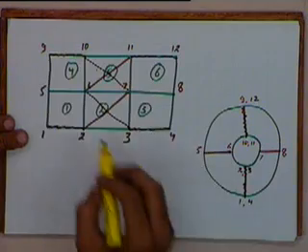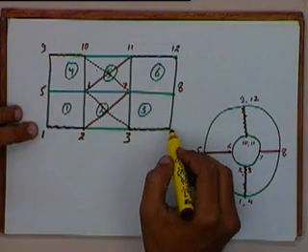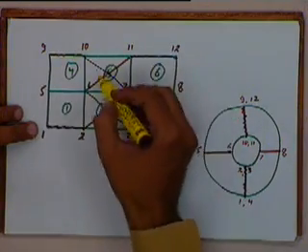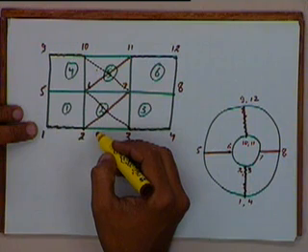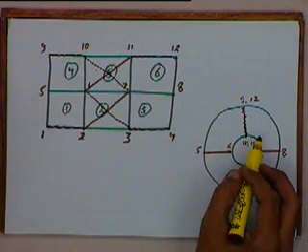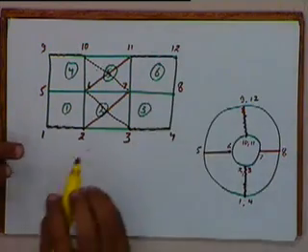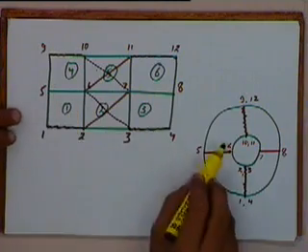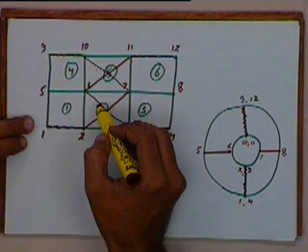And then we will get a mesh for this array, keeping in mind that these edges are merged and these blocks are void. So this way, if we have any arbitrary shape, our task of preparing the mesh will finally come down to the main task that we have to map this arbitrary shape into a rectangular array of blocks like this.